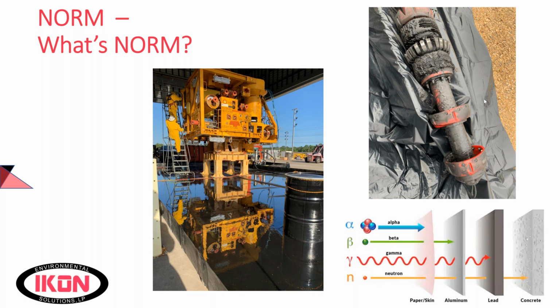So your radium is going to be back at your production pads. You start getting the midstream, downstream, your gas line, hydrocarbon filters, your heat exchangers, you name anything in the downstream, you're going to have this fine layer of lead-210. It's probably mixed with a lot of your iron sulfide pipeline rouge. That stuff's real fun to handle too. And the only way you can detect that is it's alpha and beta emitting.